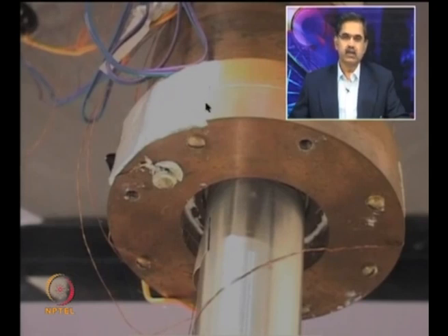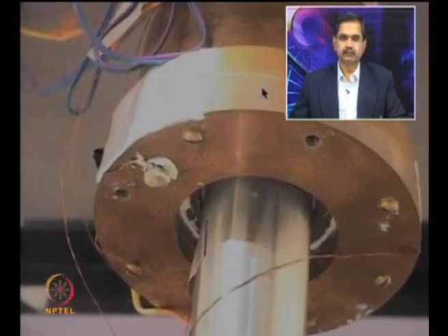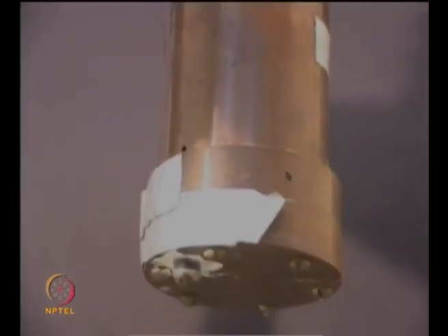All right. So, you can see that above this is the first stage regenerator. Below this, housed in the displacer, is the second stage regenerator, which, because it is a 10K cryocooler, will normally have lead balls as the regenerator material, while the first stage will have stainless steel mesh as the regenerator material. What you see also is the circuit of the first stage and second stage silicon diodes to measure the temperature. Now, this is the second stage.